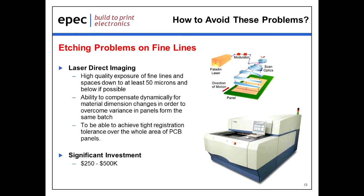Typically there's a misregistration from one corner of the board to the other. With the traditional film method, there's not much you can do about that because the film is in one plane. But with this type of equipment, it will make the adjustments as it's putting the image on the panel, which not only helps yield in a printed circuit board factory, but also helps make sure the customer is getting consistent product every time.